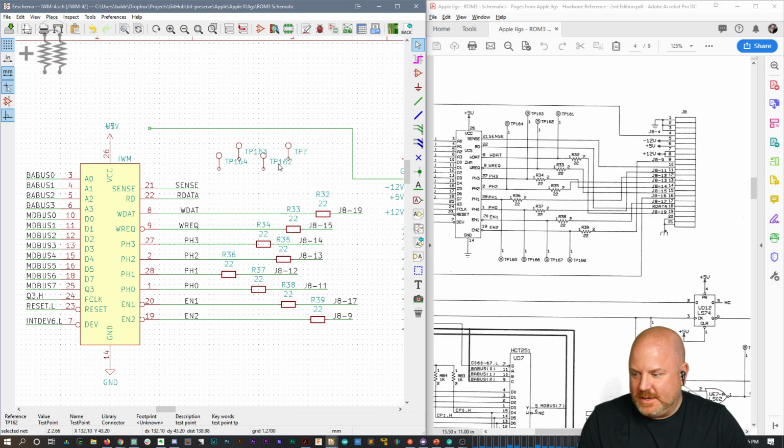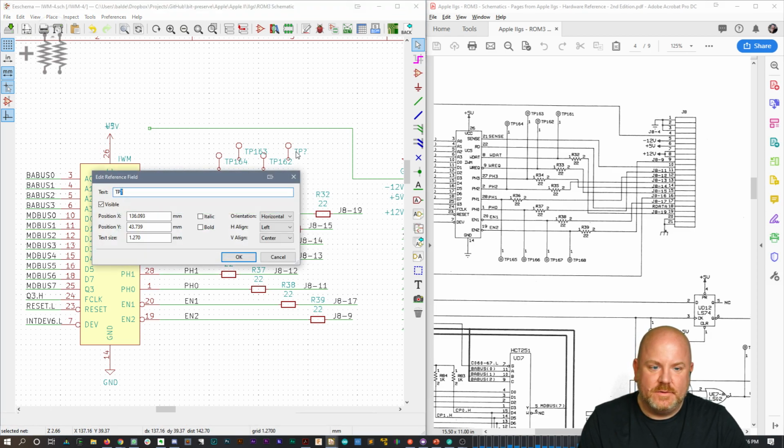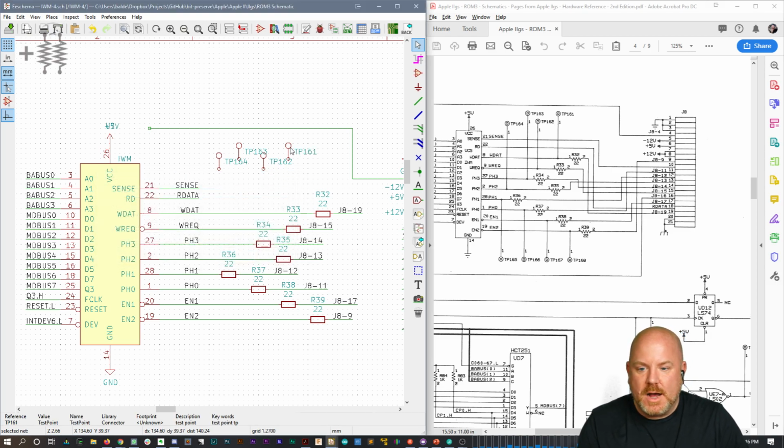Chris asks, why don't they just put the resistors inside the IC? Well, in modern ICs, you will find a lot of things like these series current limiting resistors. But the problem is resistors are really big and they take up a ton of space, and that makes it really expensive. So it's hard to justify.